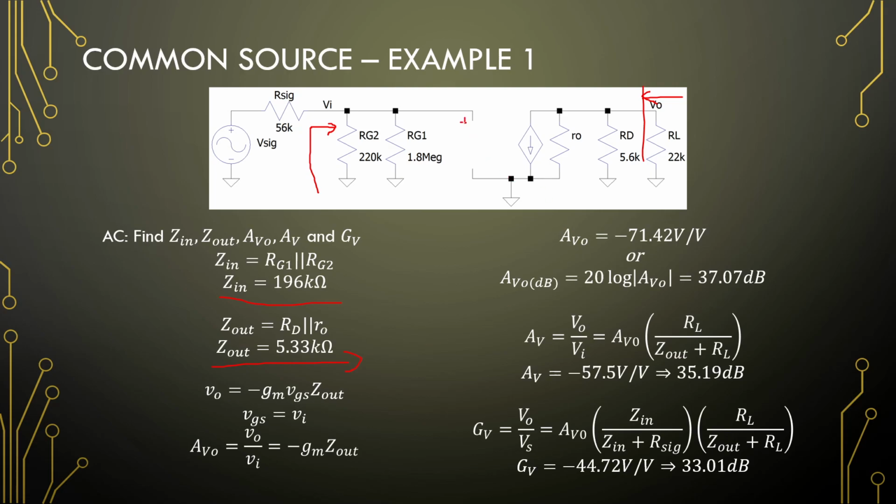Next, we have our gain. So this is still the voltage input of our amplifier, so small VGS multiplied by the transconductance of this current source, and our current source here, or the transconductance of it, can be multiplied by these resistors to give us our gain. So these two together is just our output impedance.